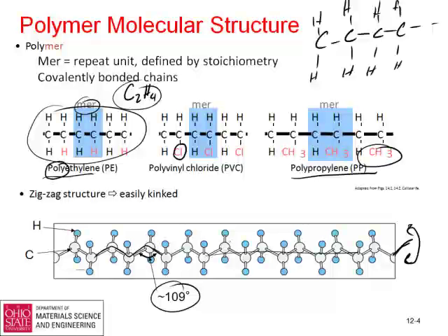As a result of this, you get basically hydrogen bonding, secondary bonding between the chains, much weaker bonds than the covalent bonds that act along them. And so these long, complicated chains also tend to stick together, with a bond that's much, much weaker. So this gives you some really interesting properties, and you can actually understand a whole lot about polymers through the structure properties of just knowing that there's covalent bonds along the chains, secondary bonds that stick them together.